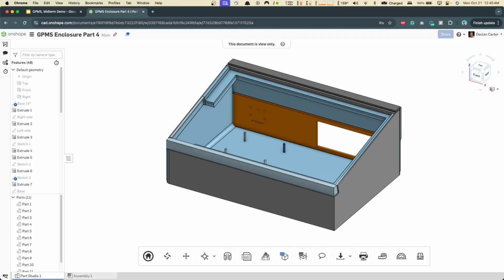Then the monitor's micro HDMI cables will connect to a 90-degree angled HDMI adapter that will then connect to the Raspberry Pi 5 in the layer below it. Here, the Raspberry Pi 5 will stay intact due to the screws at the bottommost layer. This will ensure that the Raspberry Pi 5 is safe and secure right where it needs to be. Then this Raspberry Pi 5 will connect to the camera module via serial camera interface and will be intact on the back face due to the holes for the camera to screw in.